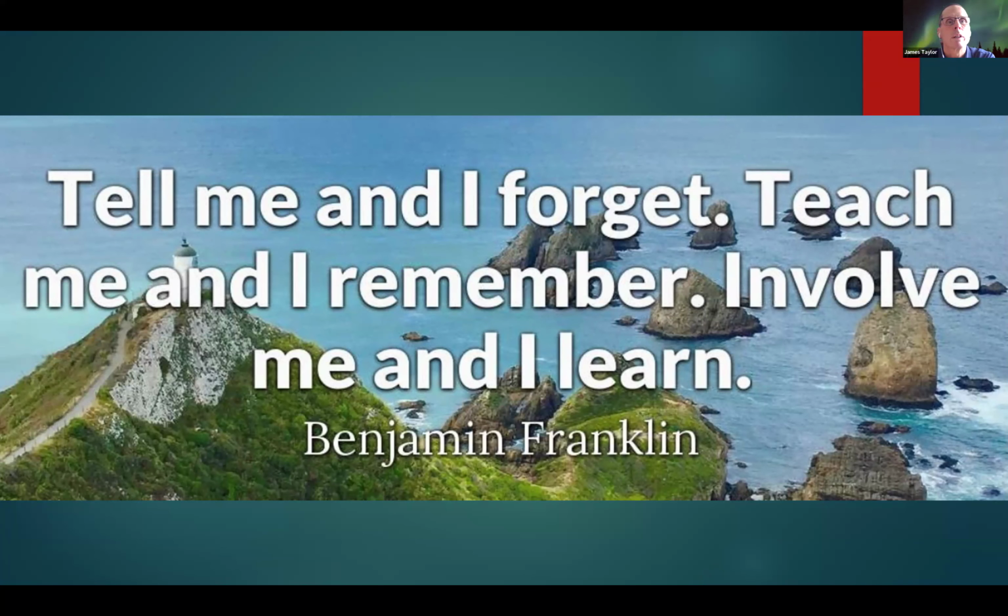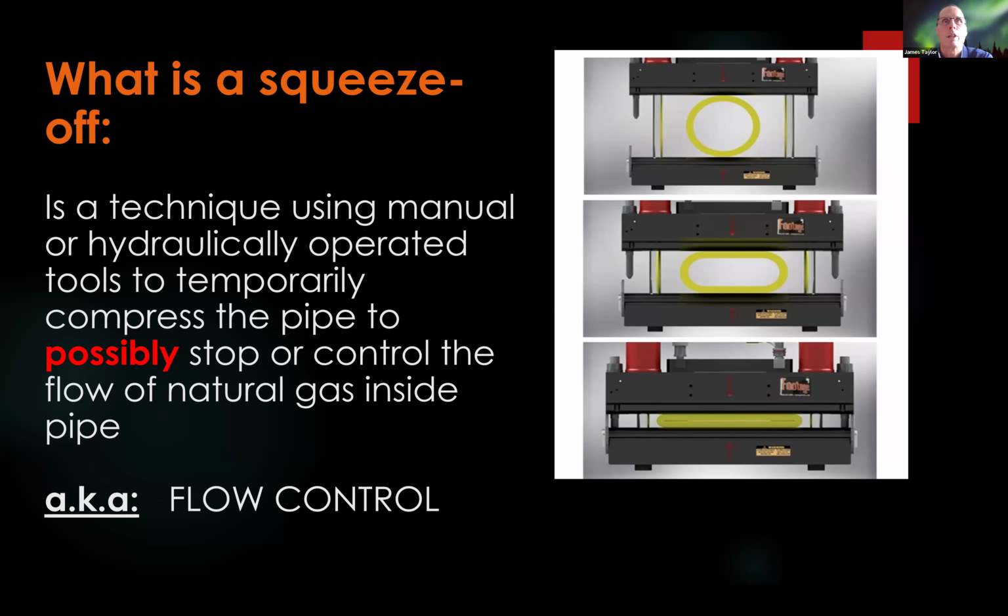Up next, we're going to look at what is a squeeze-off. This definition is right from ASTM. It's a technique using manual or hydraulically operated tools to temporarily compress the pipe to possibly stop or control the flow of natural gas inside a pipe, aka flow control. And the big word there in red is "possibly," because there's no guarantee from the pipe manufacturer, from the squeeze-off manufacturer, or even ASTM that you're going to get good flow control. So everybody knows that going in, it levels the playing field, if you will. Everybody knows what to expect. You may or may not get it, and that ASTM standard is F1563.